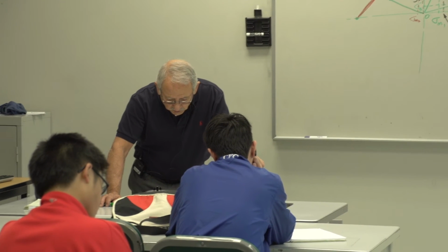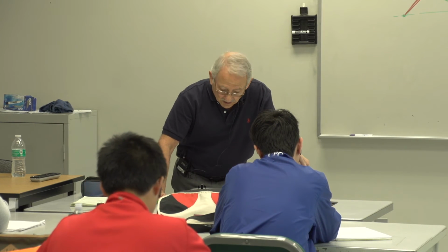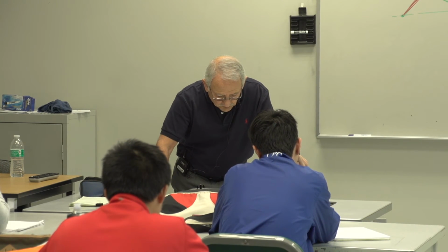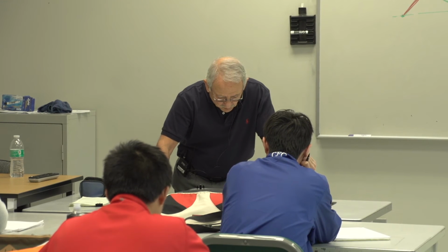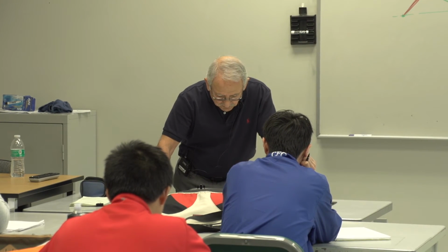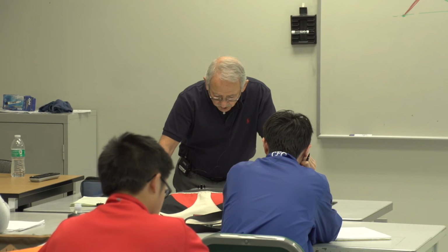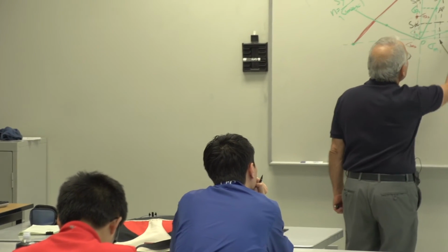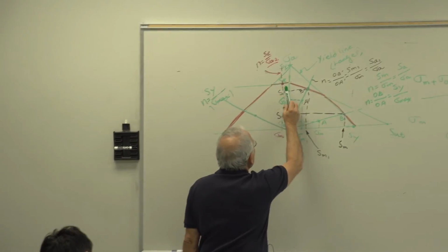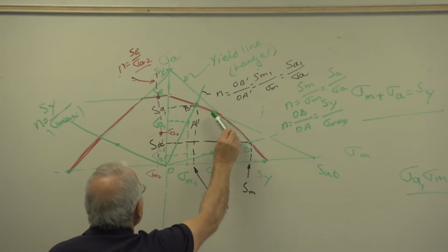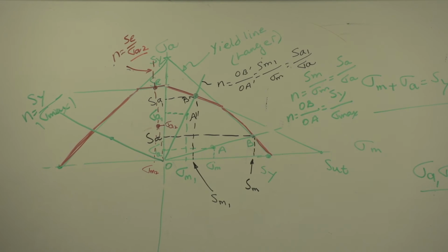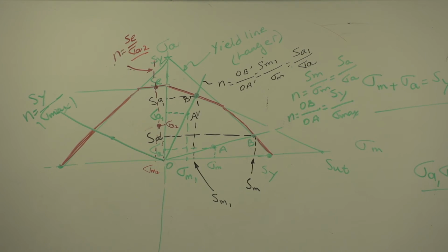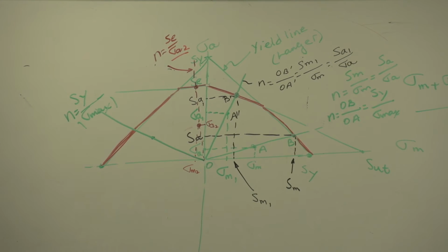Estimate the yield strength to be 90% of the ultimate strength. So you have the Brinell hardness, you can find the ultimate strength, and then the yield strength. Find the maximum and minimum latching forces. Determine the fatigue factor of safety for infinite life using the modified Goodman criteria. Modified Goodman is this red line here. This is the Goodman diagram, and it's been modified by these two yield lines, the Langer lines. So that's why it's called the modified Goodman diagram. All right?